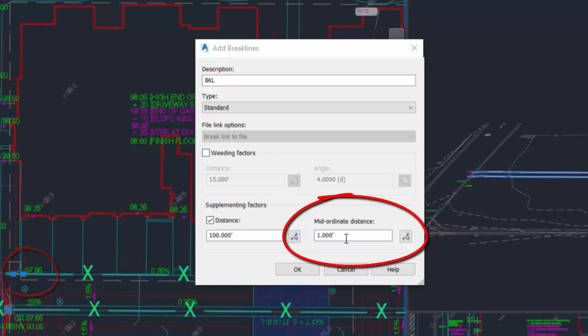Basically, it gives you the feel or look as the curve is being defined from the tin lines. Keep in mind, tin lines cannot be curved. There's no curved tin line, so this will give you the appearance of a curve. We can look at that as they get defined inside these areas.